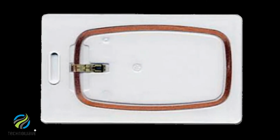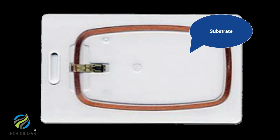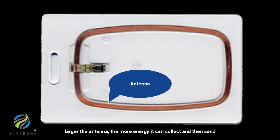Passive tags are comprised of three elements: an integrated circuit or chip, an antenna, and a substrate. The RFID chip stores data and performs specific tasks. Depending on its design, the chip may be read-only, write once, read many, or read-write. Typically, RFID chips carry 96 bits of memory but can range from 2 to 1000 bits. Attached to the chip is the antenna, whose purpose is to absorb radio frequency, RF, waves from the reader's signal and to send and receive data.